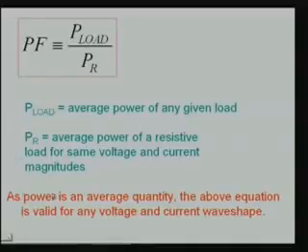As power is an average quantity, you need not bother about the wave shape. Whatever the wave shape, if you are able to measure the average powers, then you have the values of P load and Pr to measure Pf.